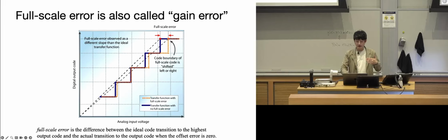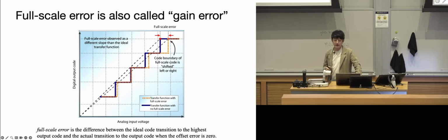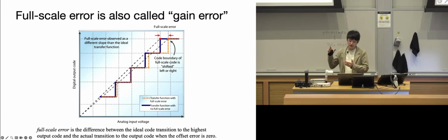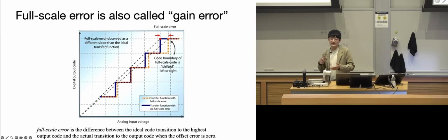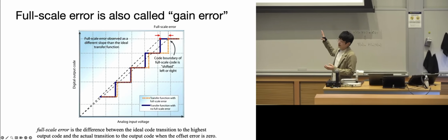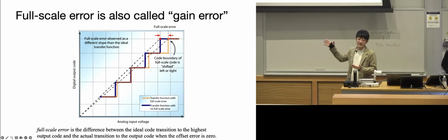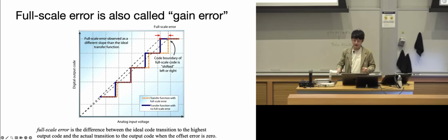So these are also kind of easy errors to calibrate. Basically, you can just sample a bunch of known values, or output DC values that are pretty accurate, and implement an easy transfer function to calibrate this out. So this is also one of the errors on the hardware that could happen, but it's usually pretty easy to calibrate.